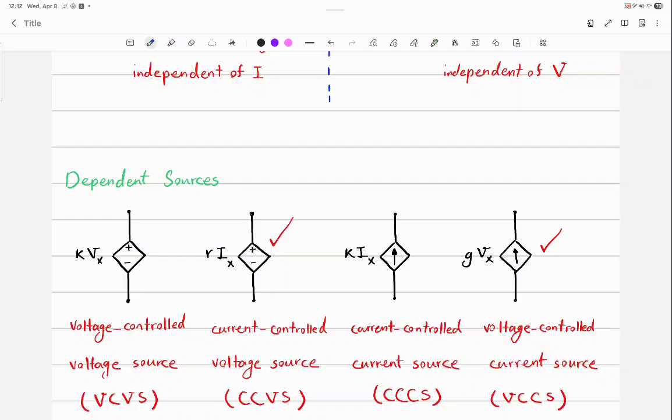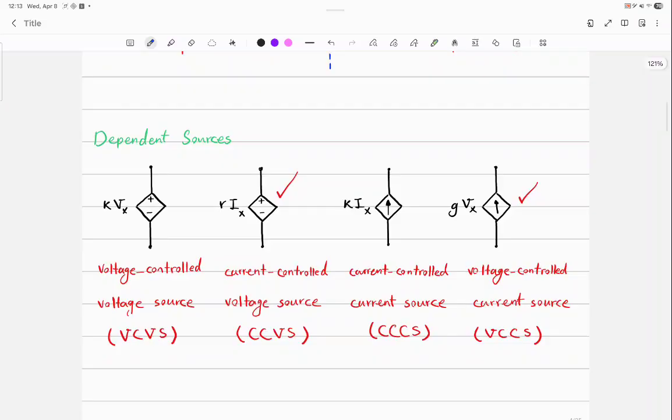Next question that could be given to you is that, what's the units of, for example, R? Sorry? Yes, volts per amps, or ohms. What's the units of G? Conductance. Well, conductance is not a unit, it's a quantity. Mhos or Siemens or ohm inverse or 1 over ohms or amps per volts. Okay? Any question?